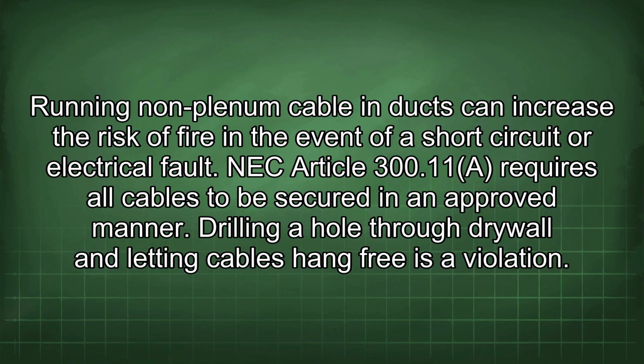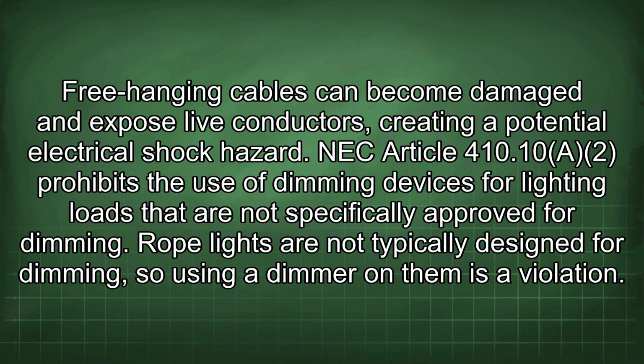NEC Article 300.11 requires all cables to be secured in an approved manner. Drilling a hole through drywall and letting cables hang free is a violation. Free-hanging cables can become damaged and expose live conductors, creating a potential electrical shock hazard.